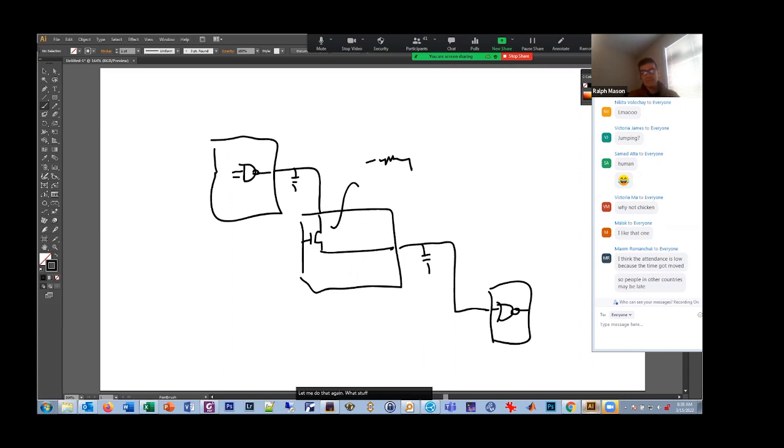Anyway, because you're going through switches, and those switches have resistance, and then there's capacitances on these lines, there's delay along here, whereas if you just had a wire, it would have almost zero resistance. So these switches that make the connections are great because they're programmable. You can reprogram these switches to reconfigure your circuit, but they tend to make things much slower than if you were in an ASIC. In an ASIC, you wouldn't have this switch. This would just be a physical wire. So that's an important concept.